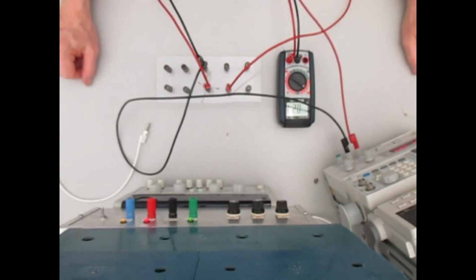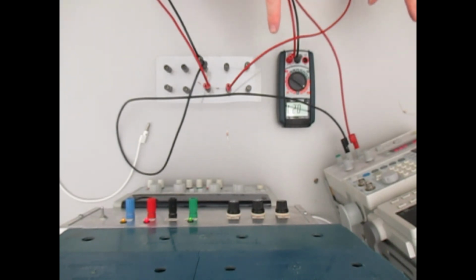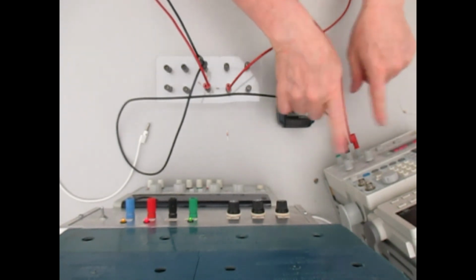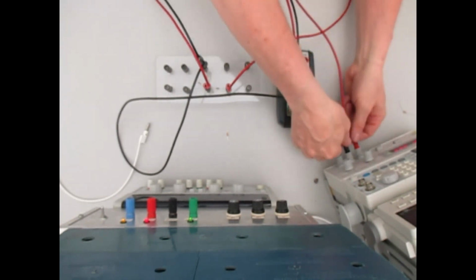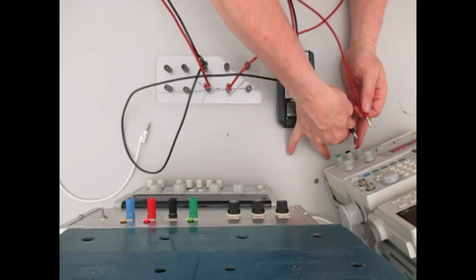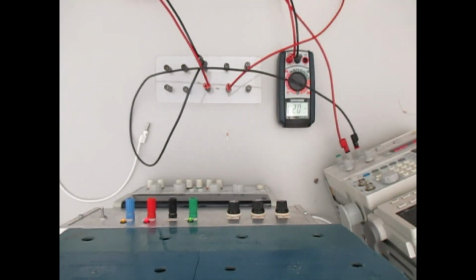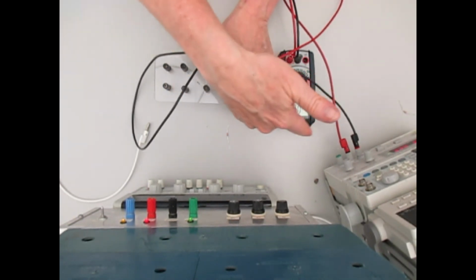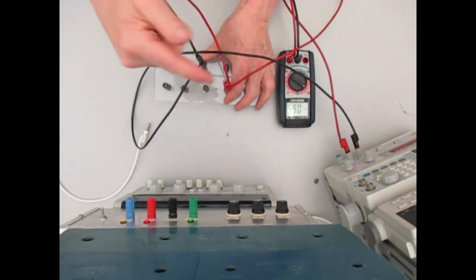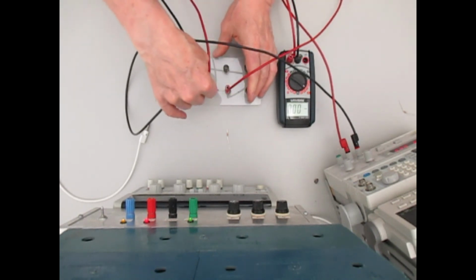Okay, so right now I've got my 0.6 volts, or 0.63, I think it was, right? And so it's supposed to be negative. All I need to do is switch the leads around and it would make a negative voltage. Use my negative as the positive. Let's just do that, just to make everybody happy. So now I'm putting negative 0.6 volts, and actually we can measure this voltage too here. Make sure it's right on. See, it's supposed to be negative 0.63. Negative 0.65 is pretty close. I can't dial it any closer than that probably.